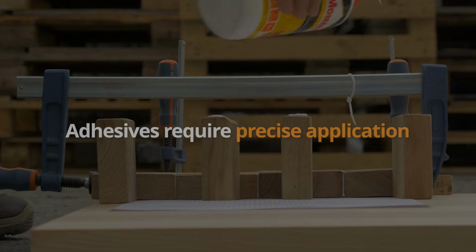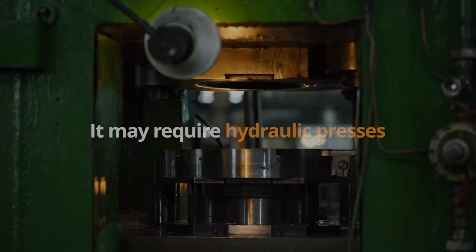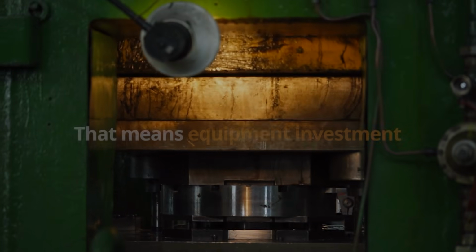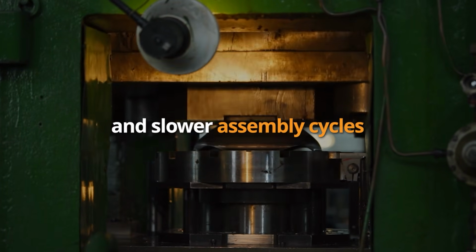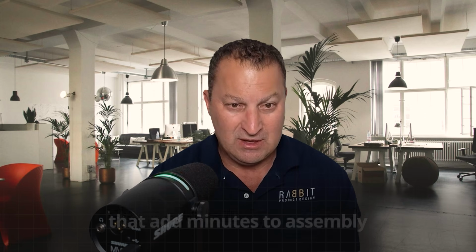Now imagine that across thousands of units. Adhesive bonding is another trap. It seems simple, but adhesives require precise application and cure time. Suddenly, your assembly line slows down, waiting for parts to set. Press-fit connections can also backfire. They may require hydraulic presses at scale. That means equipment investment and slower assembly cycles. Electronics introduce another challenge. Wire routing and connector installation, designed for prototype convenience, in production create cable management headaches that add minutes to assembly.